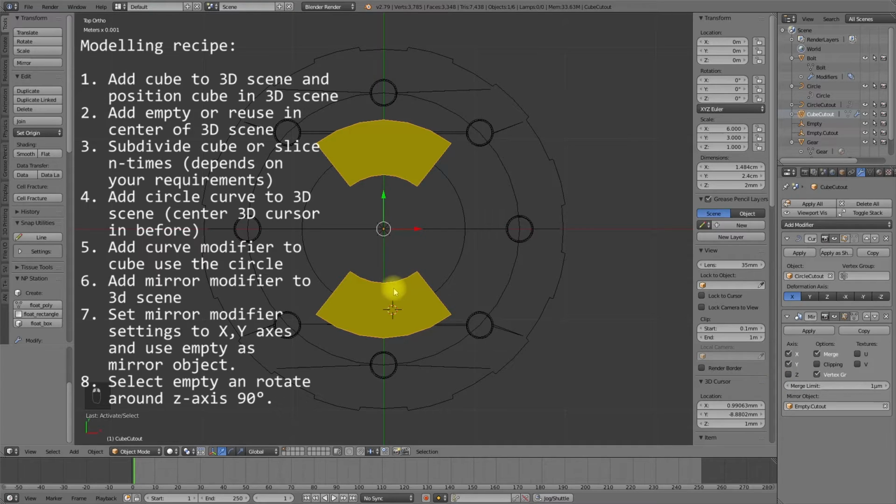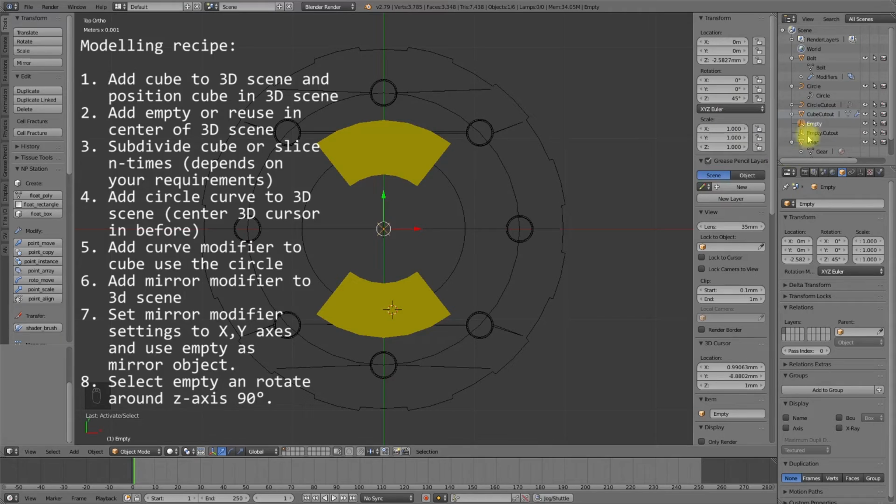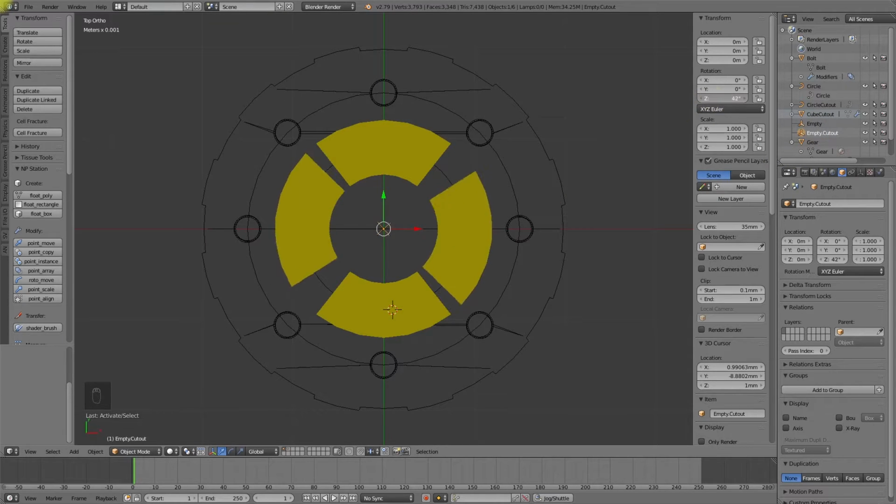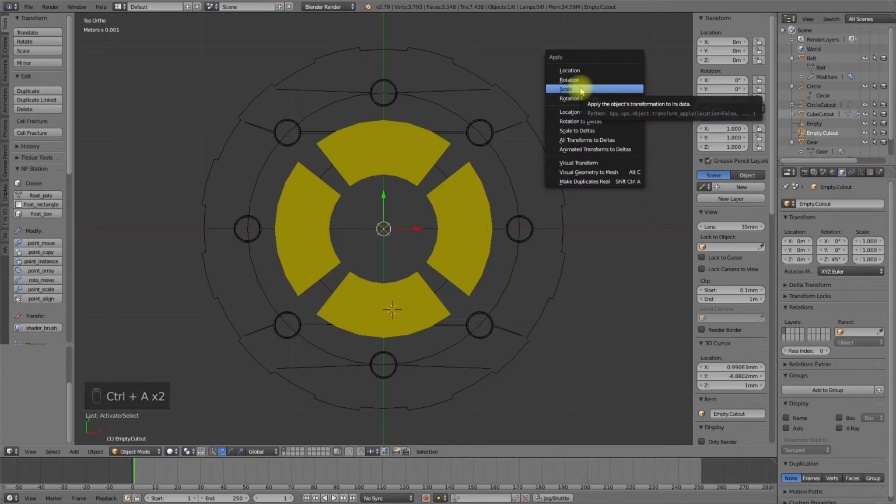The position of the mirrored instances are related to the offset of the object origin to the origin of the reference object and the distance to the mirror axis. The cutting is done again with the Boolean modifier.